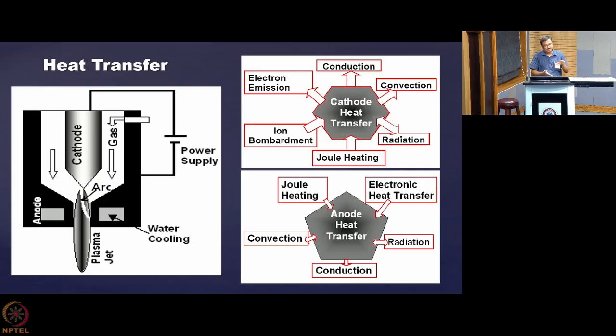But if you introduce a number of segments, then naturally the amount of heat extracted through them will be lost, and basically you are helpless. You need to give them cooling. If you didn't give them cooling, the efficiency would increase because you have not extracted heat. But at the same time, the temperature of the components will increase and that will melt them. So you are forced to give them cooling, and that way you are reducing the efficiency, because whatever heat is dumped, you are extracting through the cooling channel.